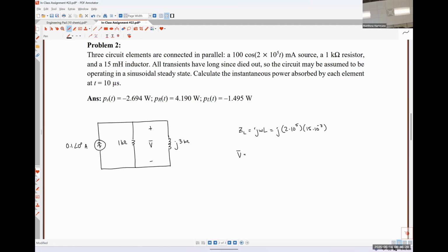Yeah, so I times ZEQ, which was what you were getting towards, except you accidentally said divide instead of multiply. Ohm's law is still Ohm's law. So V is equal to IR in DC circuits, so V is equal to IZ in these AC circuits, okay?